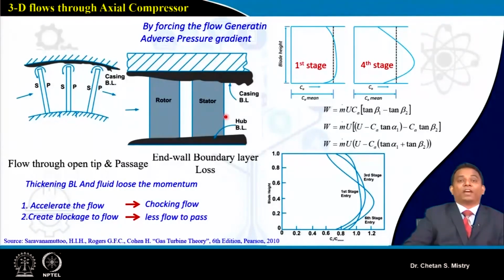Okay, and if we are considering, say, a diffusion process, that's what is happening. Along with that we are having this decreasing area, that's what is giving you acceleration of flow, and this together is making your flow more complex within the flow passage. This acceleration of flow because of nozzle action is what puts the limit on choking flow.